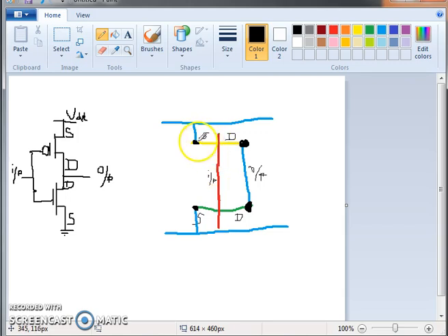After transistor formation, mention the source and the drain of all the transistors, and then accordingly do the connections of each transistor's source and each transistor's drain with reference to your circuit diagram. That's how you draw stick diagrams.